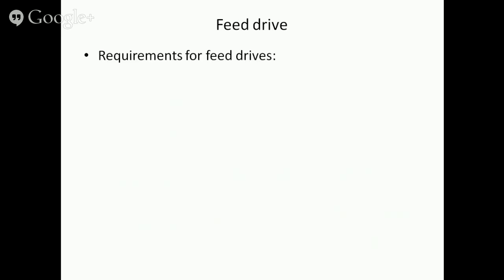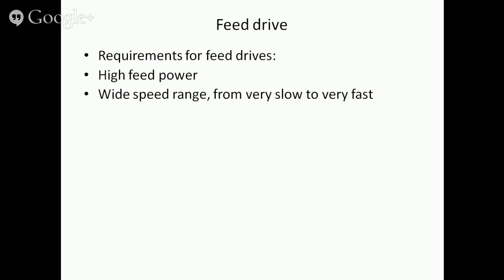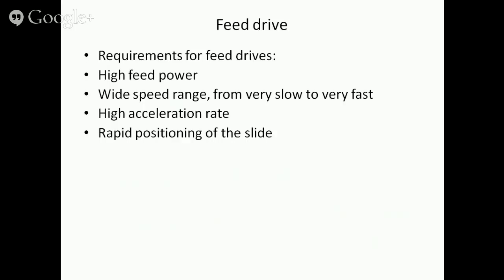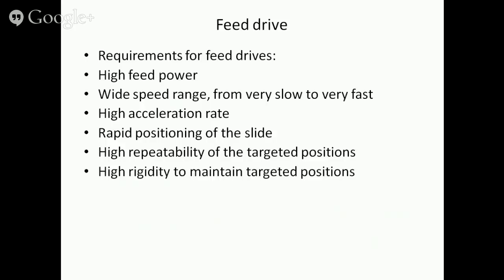Feed drives must have a high amount of feed power, a wide speed range from very slow to very fast. There must be a high acceleration rate. The slide must be positioned very rapidly. There must be a high repeatability of the targeted positions, and targeted positions must be maintained very rigidly.